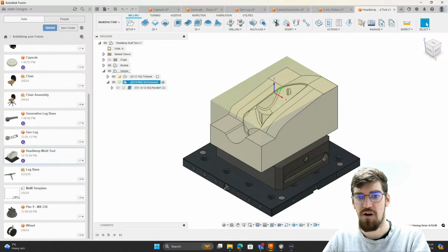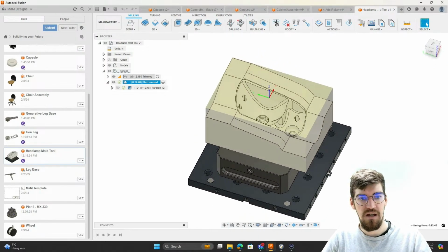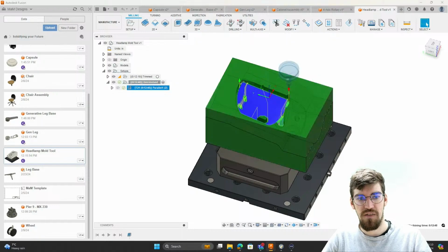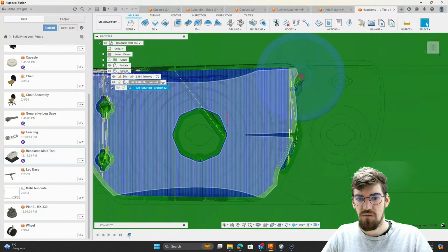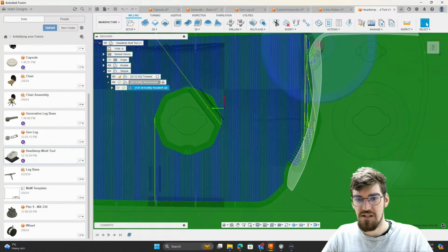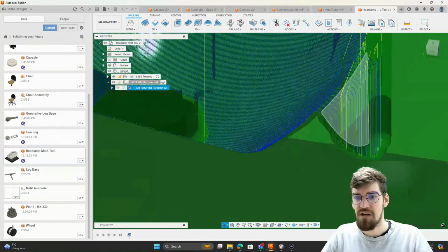So in this headlamp option, this toolpath over here, we've got an untrimmed toolpath within this parallel. So using the parallel strategy within the component itself, the way it's calculated these, it's spilled over the edge ever so slightly.